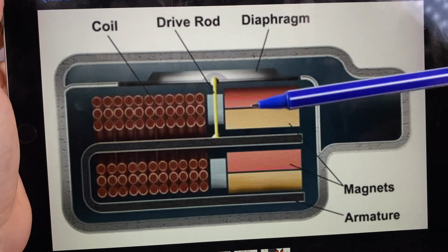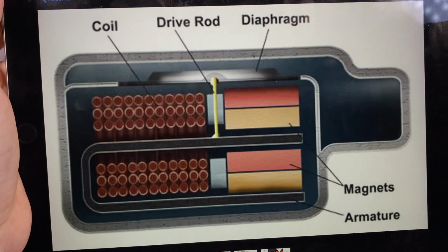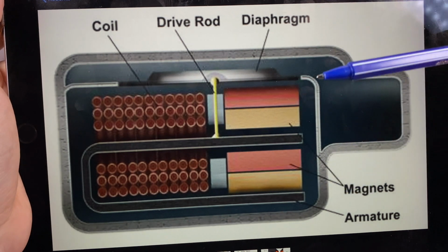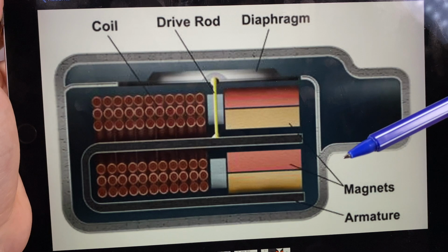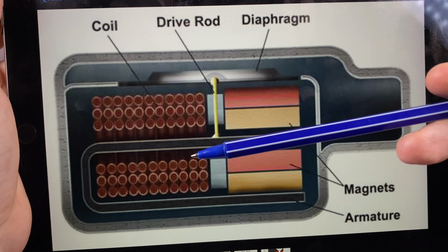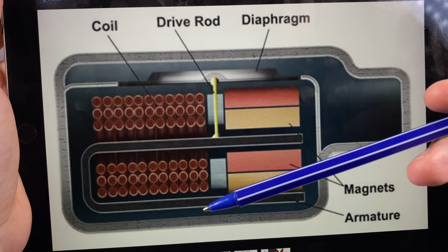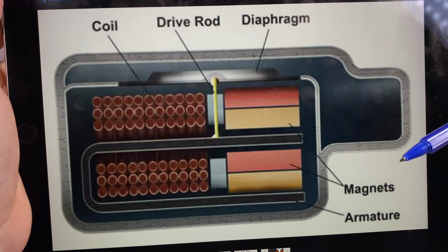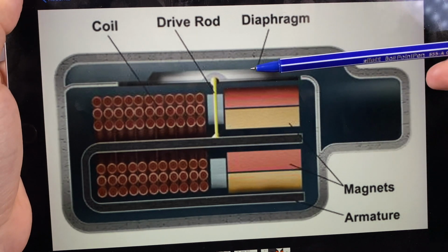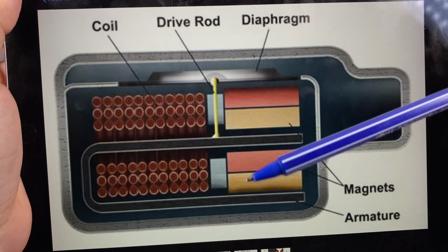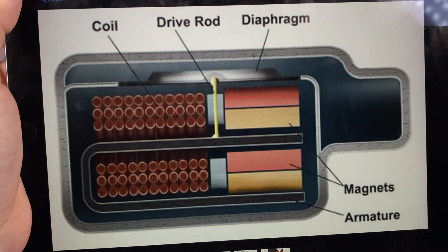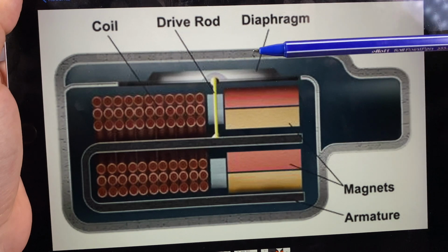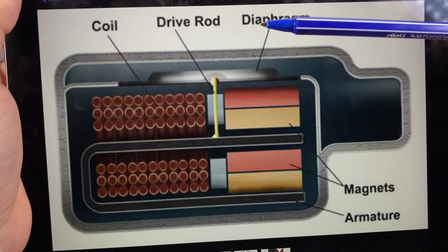For balanced armatures, we can see that impedance is like 18 ohms, for example, but usually this impedance is measured at one frequency, 1 kilohertz, and often their impedance really varies from a few ohms at low frequencies up to almost a kilo ohm at high frequencies or in the mids, so their impedance is not linear, and that aspect makes them really sensitive to the impedance of the source, to the impedance of the cable.